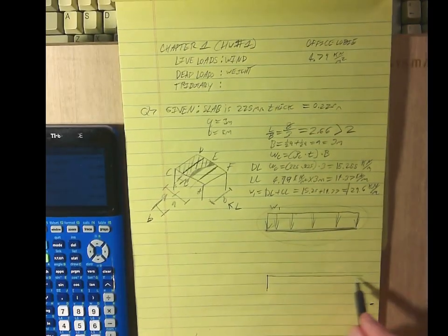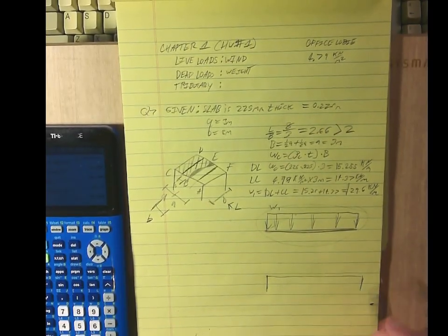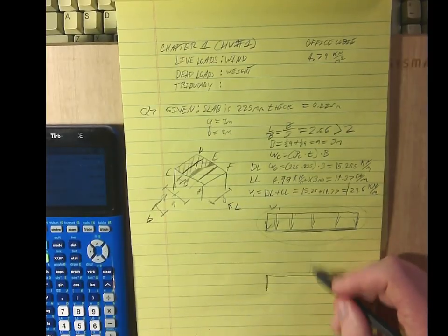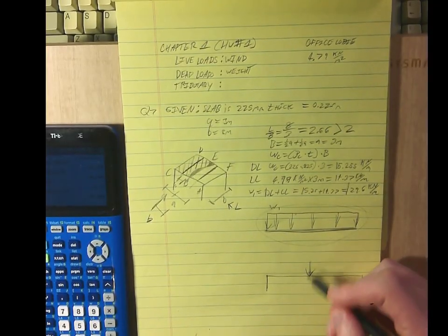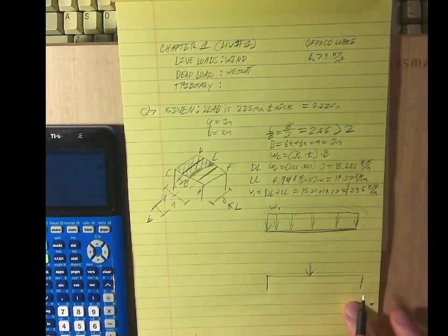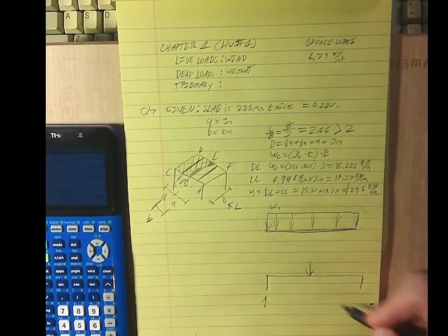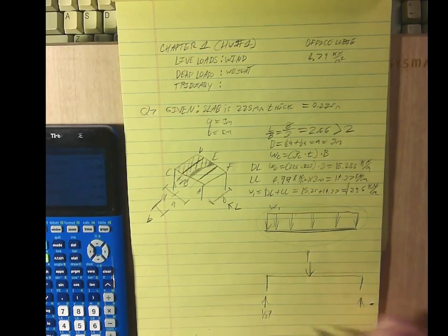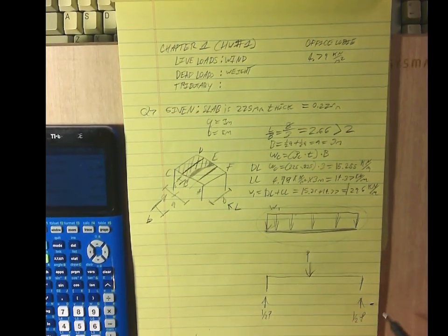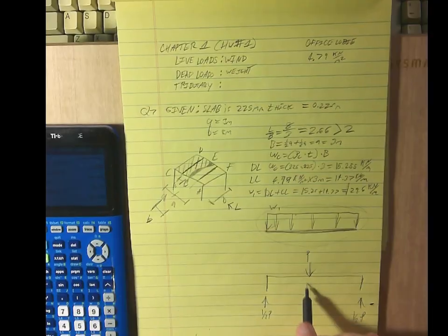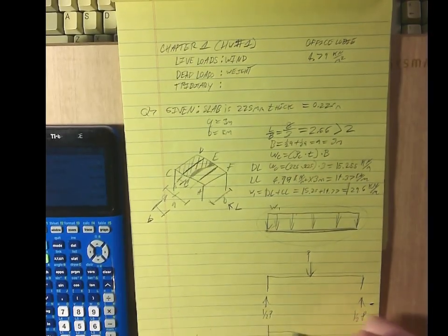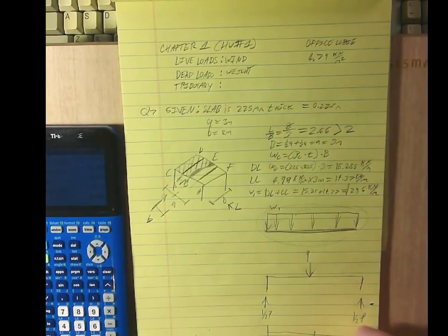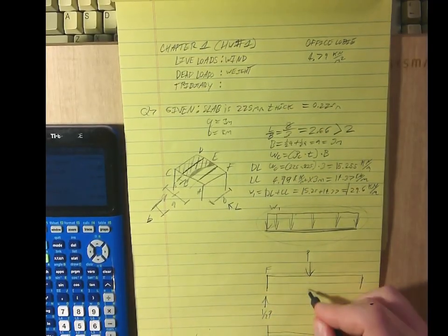This was the structure. We could actually make this a point load right here with the equivalent kilonewtons per meter over this many meters. And then these supports right here, this is P, this is 1/2 P on each support. That's how we could just break that up. Like that. And this is on FED.